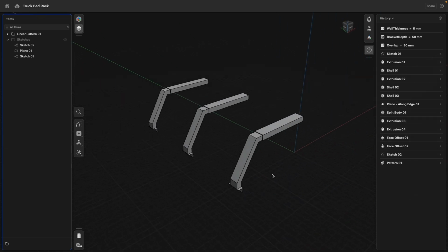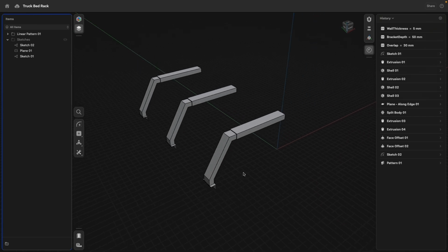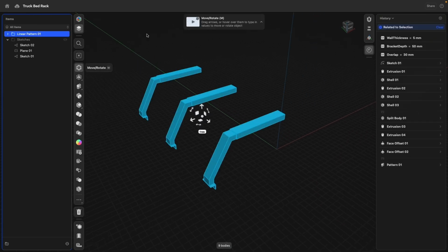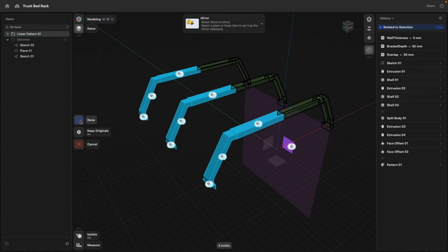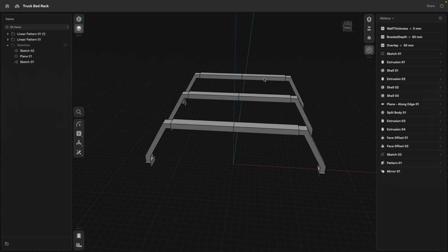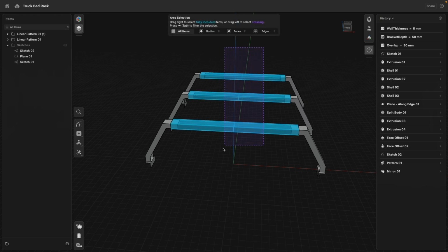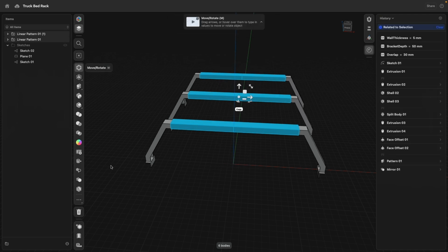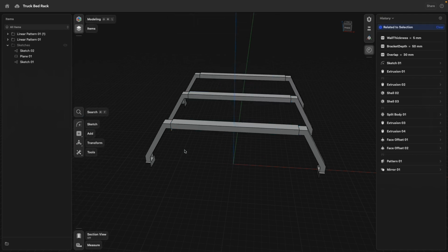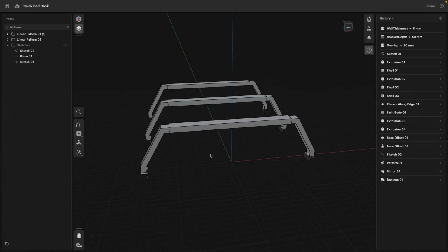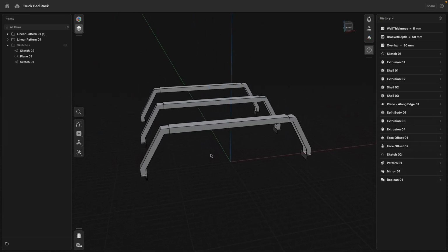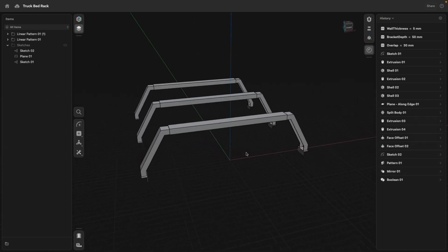So this is actually looking quite good. Perfect. Now I could select all these parts and go to a mirror command, mirror this over to the opposite side, left mouse button, click and drag right to the left side, select the bodies, and then we fuse those together. There we are. Pretty cool. This actually looks really, really nice.